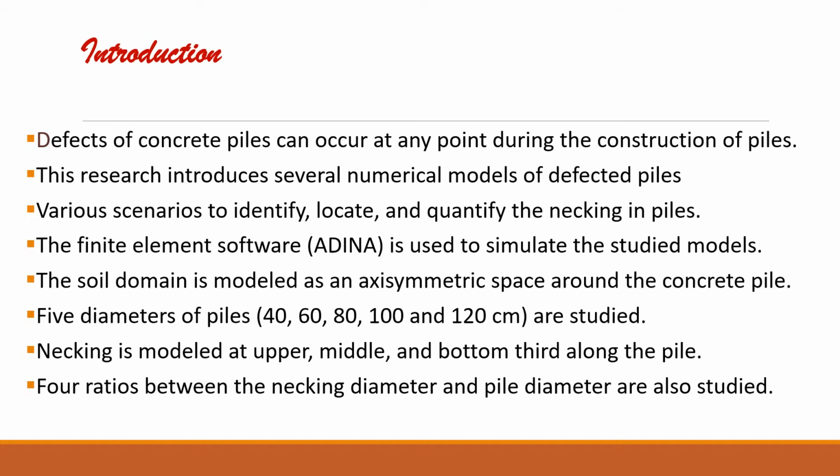This research introduces several numerical models of defected piles, various scenarios to identify, locate, and quantify the necking in piles. The finite element software ADINA is used to simulate the studied models. The soil domain is modeled as an axisymmetric space around the concrete pile.